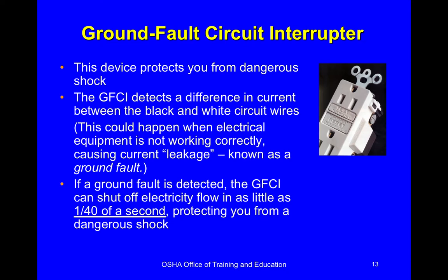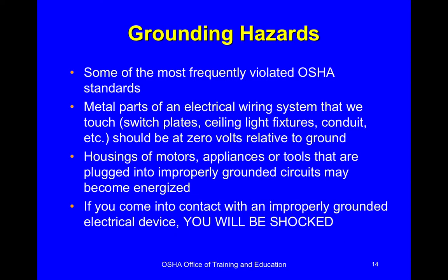Ground fault circuit interrupters, GFCIs, these are meant to protect people, okay? It will sense a potential difference there or a leakage to ground, and it will trip. Supposedly this will happen below the threshold of pain, but I wouldn't test it if I were you.